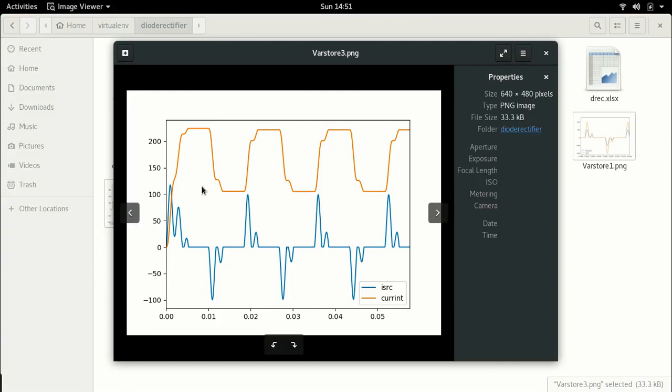Yeah, so ideally what has happened is it is now summing, and it gives you this fairly weird output. And you can see here the summing usually takes place in this part. It stays constant because after that the current is 0, and it returns back to a lower value when the current is in its negative wave, has a negative value. So this kind of seems like a working simulation. It gives you the idea how we can use static variables to do things like summation.